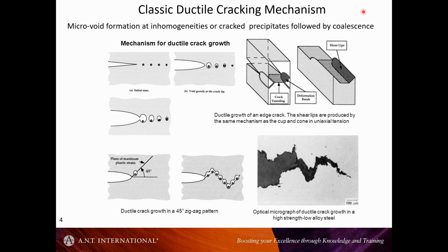And again, what's happening here is that you have some stress intensification close to a crack tip that can, especially when you have an inhomogeneity, which is the precipitate and the matrix, generate sufficiently high stresses to create this decohesion, although I'm not sure.